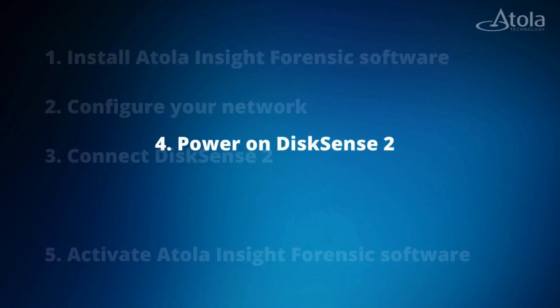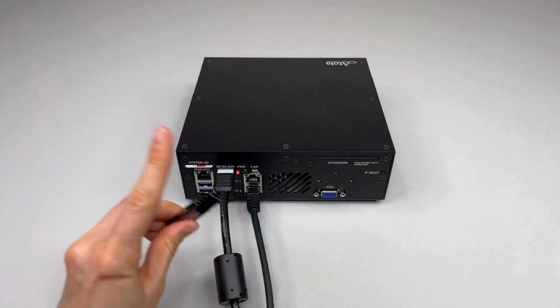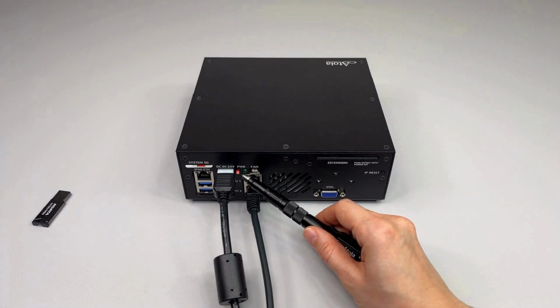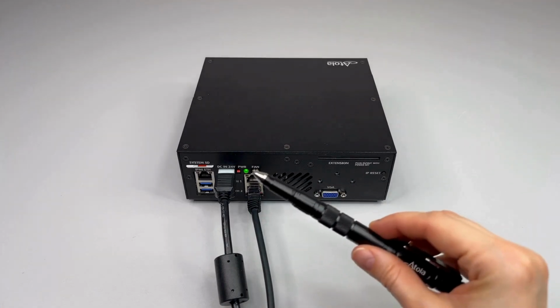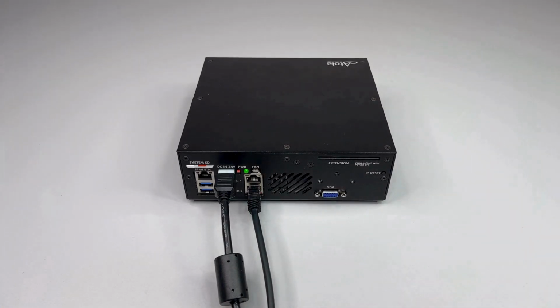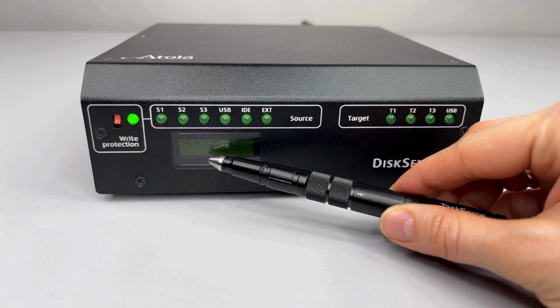Now we are ready to power on DiskSense 2. Make sure that there are no USB devices plugged into the unit. Using the power switch on the back panel of DiskSense 2, power on the unit. Wait for the power LED on the back of the unit to stop blinking. When booting is finished, the unit's IP address appears on the IP screen on its front panel.